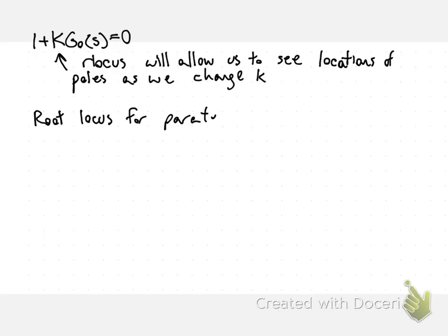Well, we're doing root locus for parameters, and I want us to consider the example problem from homework 7, I believe it was, where we had a system represented with a characteristic equation s squared minus mu plus 2 s plus 2 mu plus 5 is equal to 0. And from the homework we had that this system was neutrally stable at mu equals -2 and -2.5.